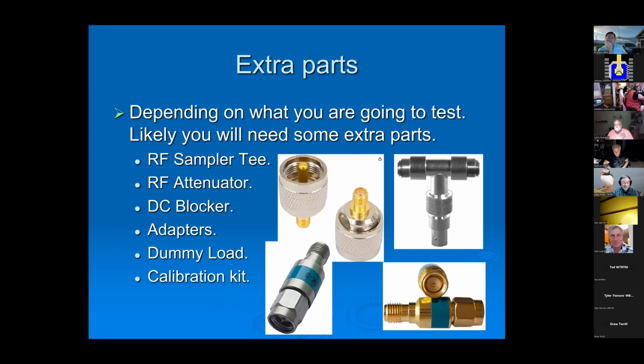You're typically going to want some RF attenuators. Down in the lower right-hand corner, there's a couple of attenuators, because you can't always get that RF down to the level that you need to keep from destroying the instrument. Understand, going into that device, they will tell you a spec. It can only receive a certain amount of power. It'll be expressed in dB.